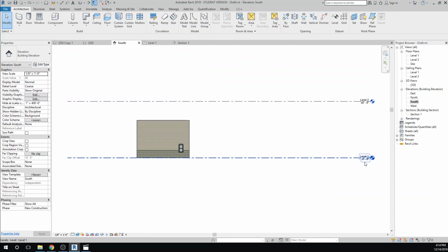And level 1 is typically where we want our first floor to be, as I said, and that would be really more at the top of the foundation. The way we are aligning this stack wall is to the bottom of the foundation. So I want to make some adjustments here. I want to make the foundation sit lower than level 1.